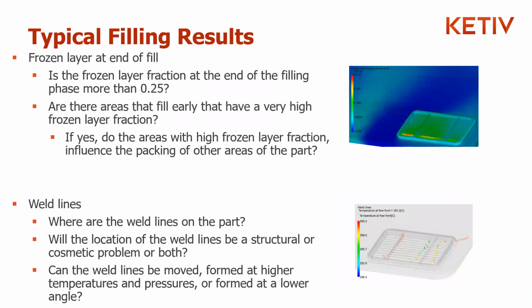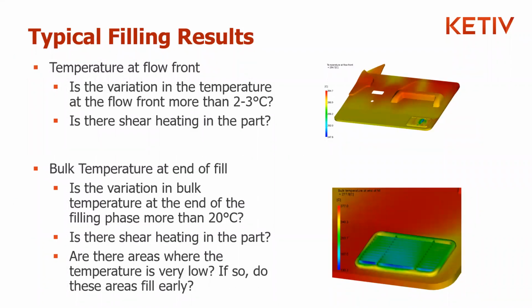And yeah, it's a game of averages, right? So as you go from a single part to multi-cavity, you've got shot-to-shot variation out on the manufacturing floor, cavity-to-cavity variation, material lot variation. So narrowing this down in the theoretical world is a lot easier to do than the real world, and that's kind of the game you have to play. It's like, how do I make this as uniform as possible so I don't have quality criteria fighting each other out on the floor? Yep, absolutely. And all this while keeping in mind your molding and manufacturing capabilities.